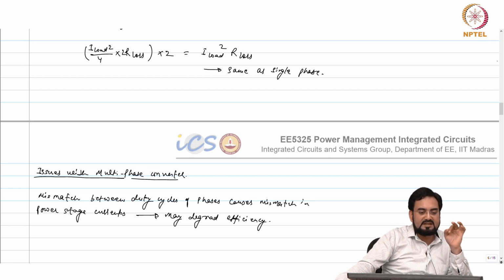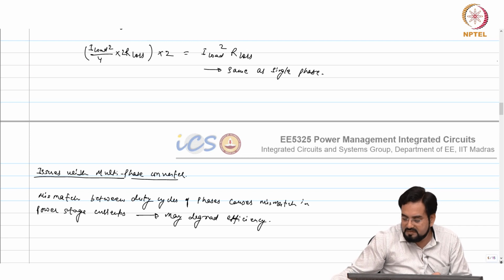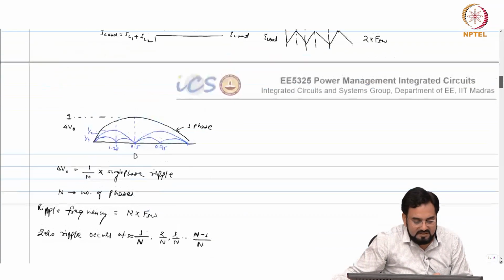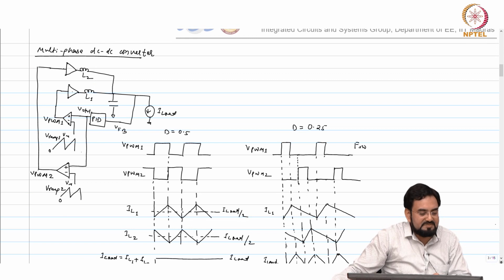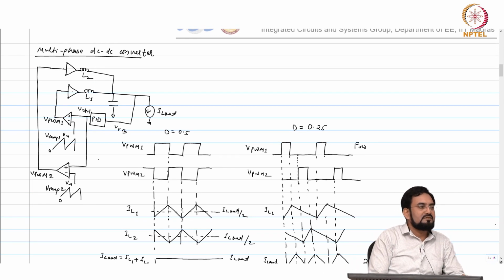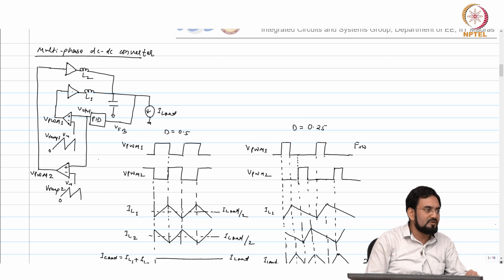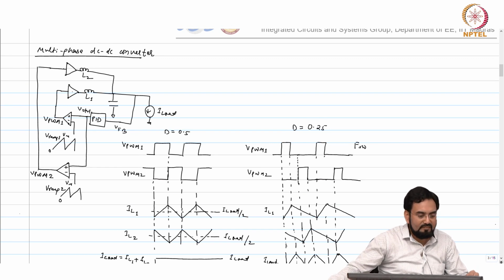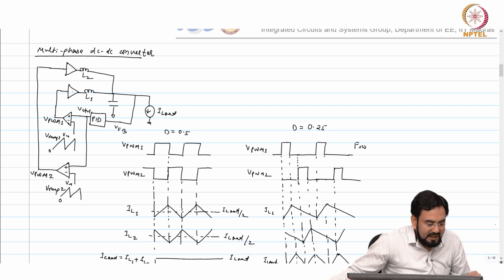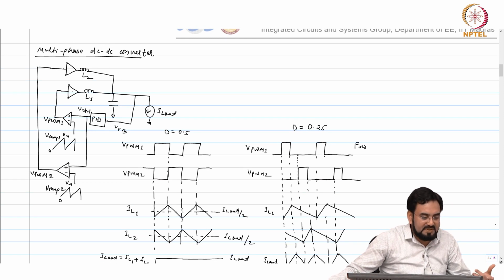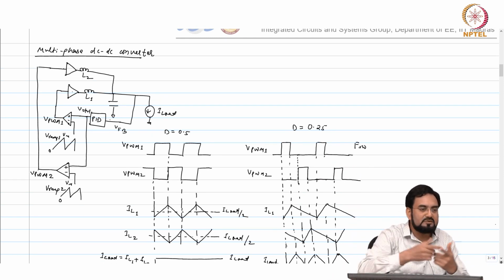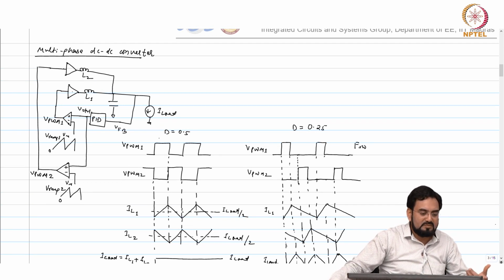So, we are using a single control voltage. So, who will cause the mismatch here? Ramp will cause the mismatch, or comparator offset, or let us say delays in the comparator, that will also cause mismatch. And ramp, obviously, I mean, we are charging a capacitor with a current, and those two currents may have a mismatch. And that is why we require current balancing.